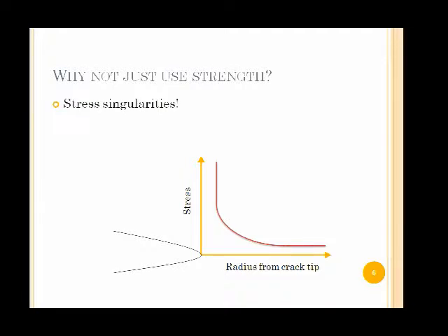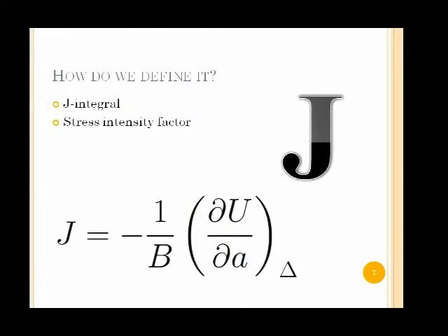And these stresses, theoretically, go to infinity as you get exactly at the crack tip. So there's a singularity there. And we need a way to calculate how much stress is actually at this crack tip as opposed to throughout the entire structure, so that we can predict if the crack will go forward, will it start, and how strong the actual concrete pavement in this case would be.